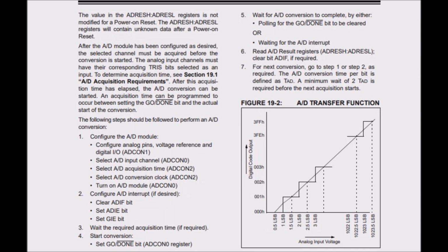An acquisition time can be programmed to occur between setting the GO/DONE bit and the actual start of the conversion. The following steps should be followed to perform an AD conversion.